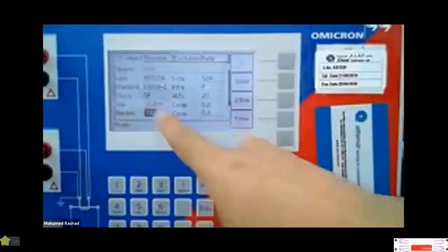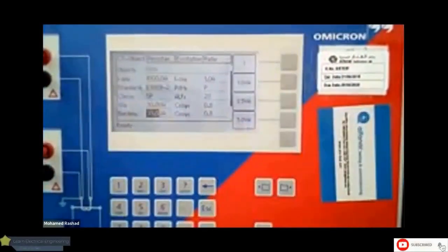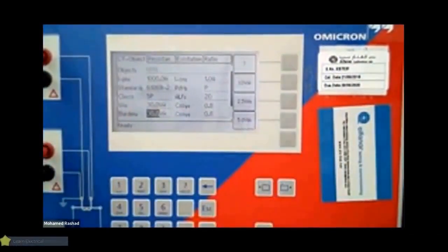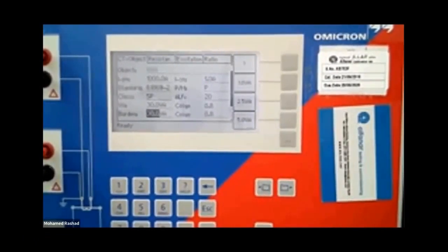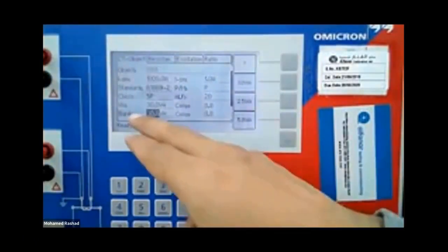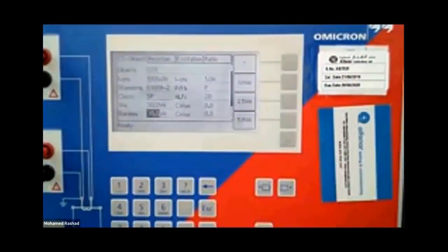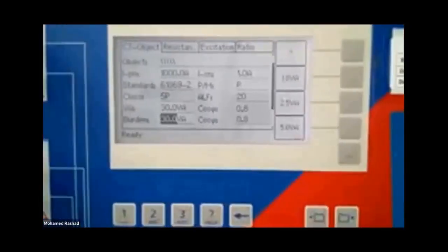He said, well, I will give you the allowance, because your CT is actually connected to a circuit. And you have in the station a circuit, for example, from the beginning to the end over a long distance. So the resistance of this entire distance matters. Here you can simply enter the operated burden, which is the actual burden you have. And based on that, I will tell you in this case what your accuracy limit factor should be.